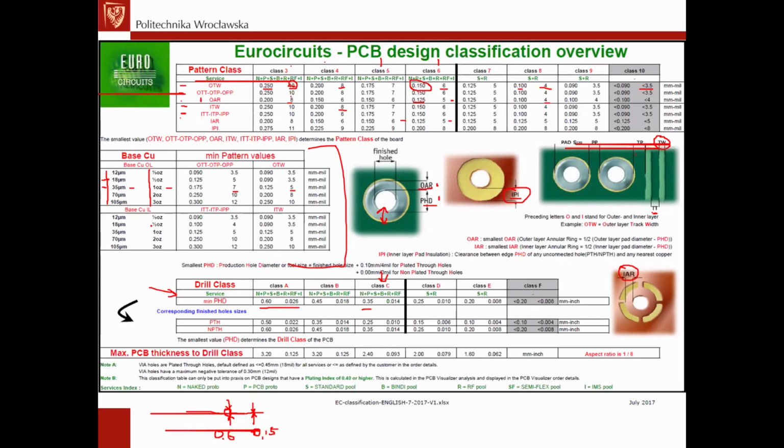18 microns, what's the penalty? Because it doesn't have to be more expensive, actually. But what's the penalty of using thinner copper? The penalty is the resistance of the tracks, which means that they are thinner. We'll talk about the resistance of the tracks in a moment, but to keep the cross section area the same, we must extend their width because they are thinner.